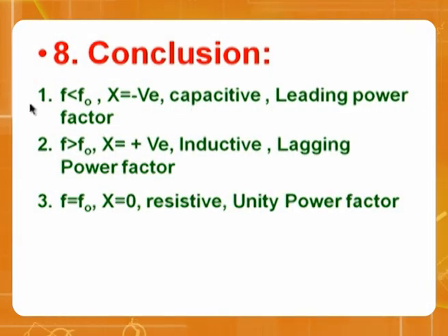Now the conclusion. F less than F0, X is negative, capacitive. F greater than F0, it is inductive. And at resonance, it is resistive, with unity power factor.